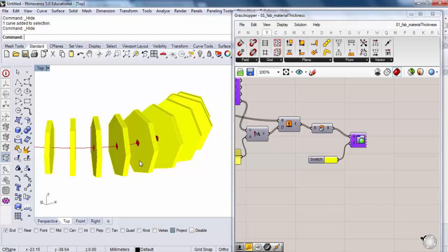Do we need to put more extra tolerance? Or just 3? Just 3 is good because the laser cutter has a slight thickness to it. Oh, yeah, so it gives you a bit of leeway. Yeah, and with these, you could make them nice for sure, but the idea is that you just make quick prototypes and test things with it.